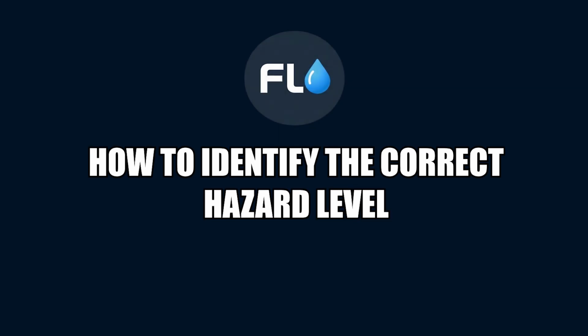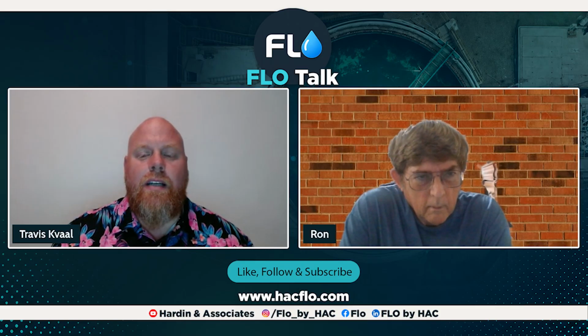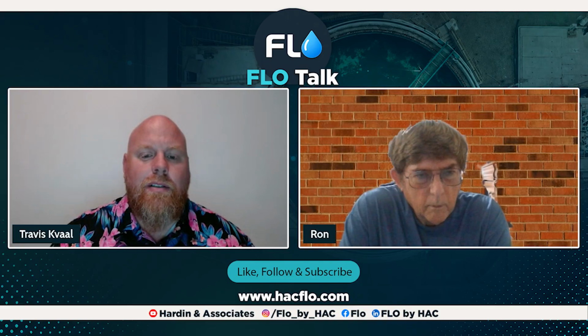Yeah. So when we have a new assembly installed, or when we've got a new cross connection that we've got to deal with, when you see that new assembly, how do you know whether it's for the right hazard level or not? Well, one of the first things we need to do, like we talked about a little bit earlier, is ask: does it have an OSSF? Is it on irrigation? Is it on the domestic side of the meter? And exactly what is it, a commercial, is it a residence? Exactly what do we have going on, and where are the lines running? This is where it's so vital to do our CSIs, and those kind of things are kind of preliminary on the CSI and kind of look around.